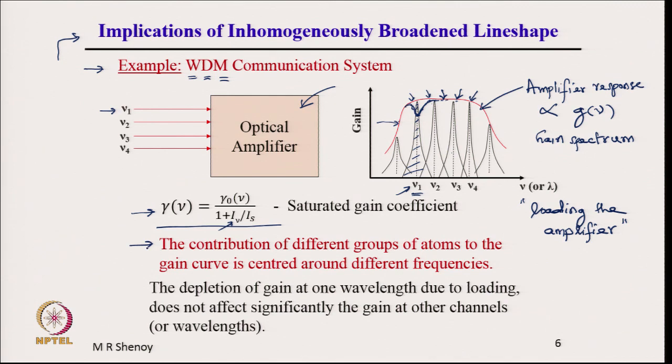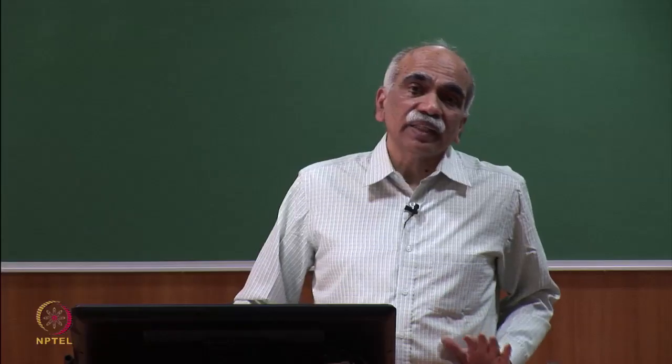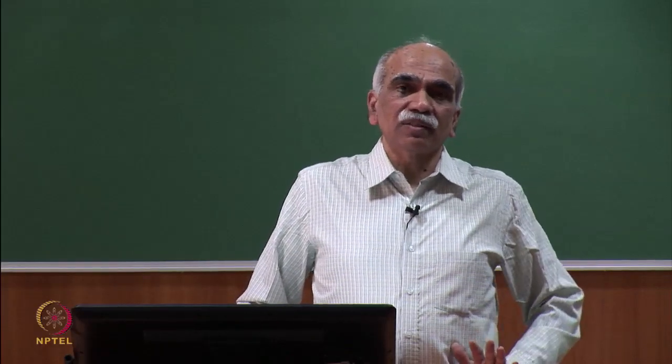The contribution of different groups of atoms to the gain curve is centered around different frequencies. Therefore, the depletion of gain at one wavelength due to loading, that is due to an input, does not significantly affect the gain at other channels or wavelengths. This is very important in a WDM communication system.